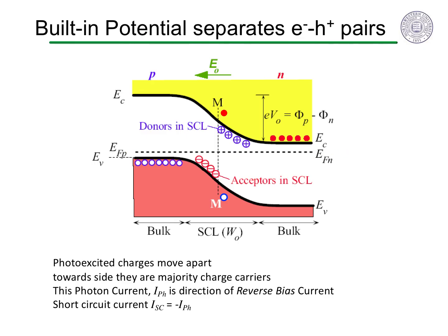The drift potential is the same as the electron potential energy, so we can imagine the non-equilibrium electrons as being excited into states that are bent like the conduction and valence bands shown here. The electrons then slide down the conduction band towards the n-type side, and the holes float up towards the p-type side. Note that this is the direction of a reverse bias current. Forward bias is to drive majority electrons and majority holes towards each other. Here, the electrons and holes are moving in the opposite direction.